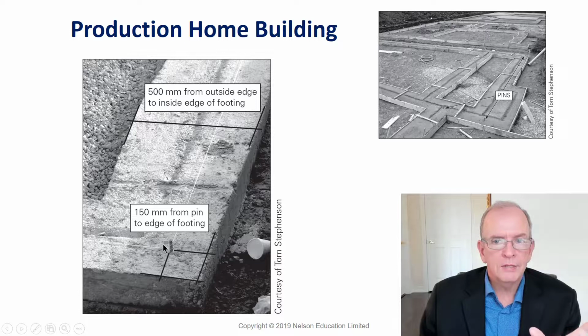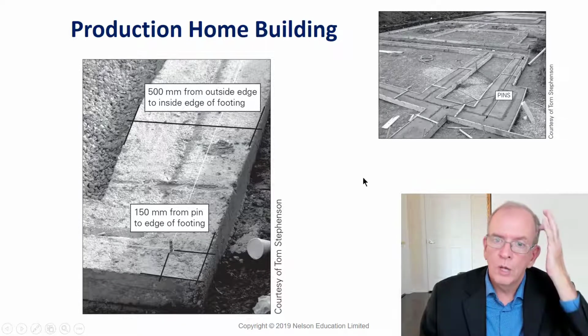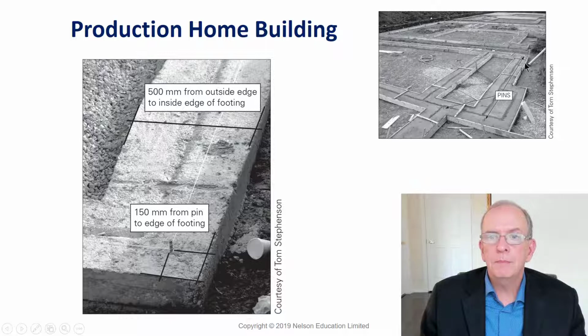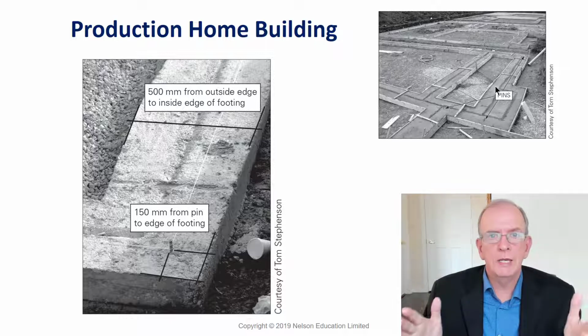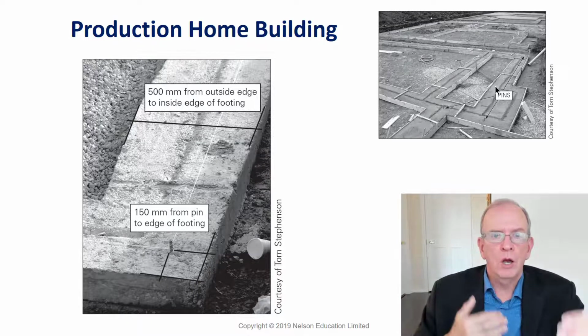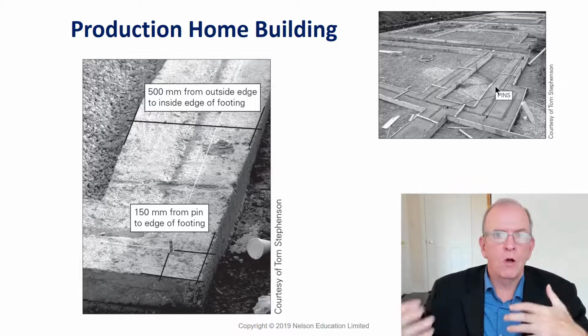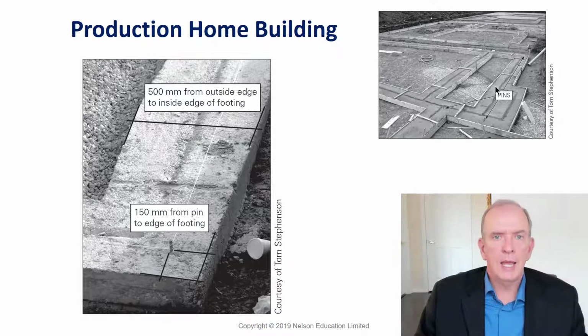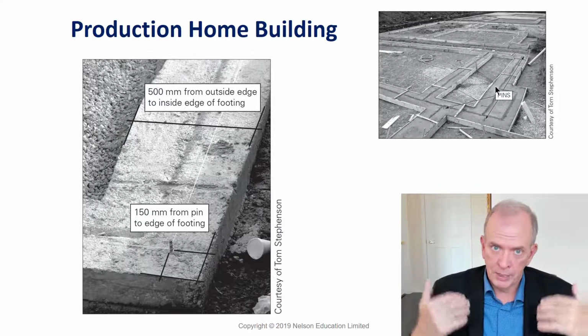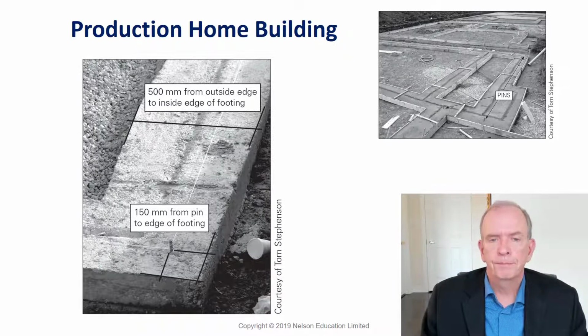So those pegs give us all the information we need to know so that all of these footings can be laid out. And the pegs, you can kind of see they're in the key places that everything could be referenced from them. And then you can lay out the footings, which are based on your site plan and based on your foundation plan for the actual house, so that your house is situated in the right location on the property that fits all of the zoning requirements and permit requirements, which we'll get into in lecture 1B.